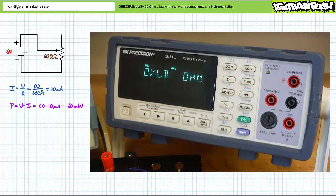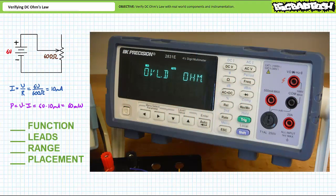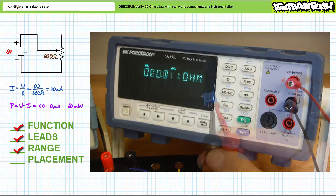Let's use an ohm meter to set the potentiometer to the desired 600 ohms of resistance. Use the checklist to do so. Function, leads, range, placement. Function. Choose the ohm meter function. Leads. Black lead into the black common hole. Red lead into the hole marked with an ohm symbol above it. Range. Don't worry about it. This particular DMM is auto-ranging, meaning it will choose the most appropriate range to obtain the most precise results.